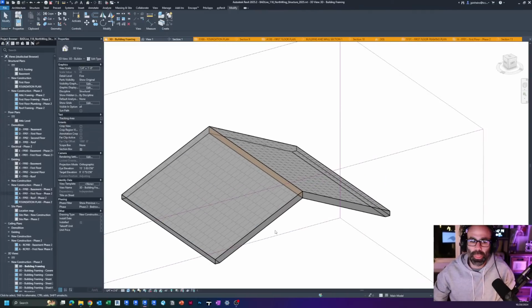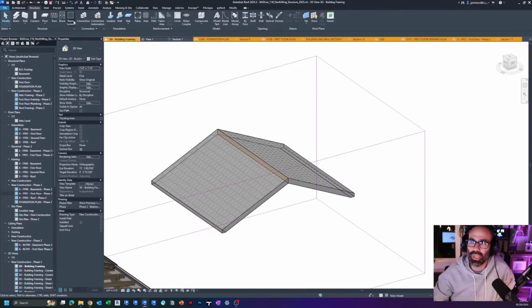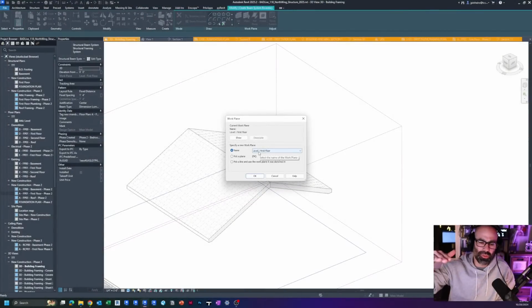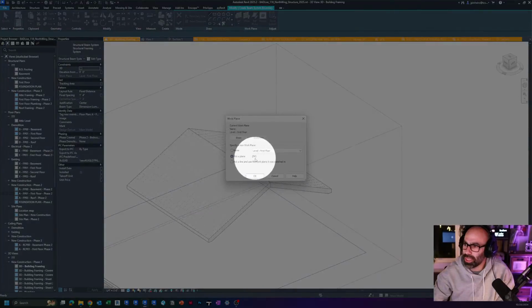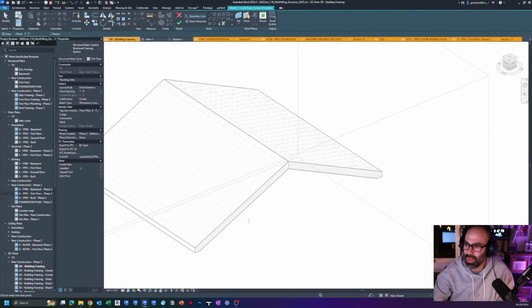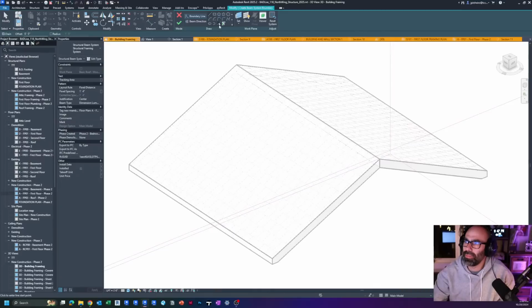So once you have your roof designed, or maybe it changes, it's okay if it does, but once you have it generally designed, then it makes the beam system part of the roof super easy to do. So if I go over to structure, just like I did with the floor, I go to beam system, right? The difference is when I set my work plane, which is up here, I click set work plane. I'm not going to use first floor. I'm not going to use roof. I'm not going to use a level. I'm going to pick my plane, which is this option down here. I'm going to click OK. And now I'm going to pick the top of this roof. Okay, so now I'm working on the top of this roof. That is my sketch plane. And now there's different ways you could sketch it.